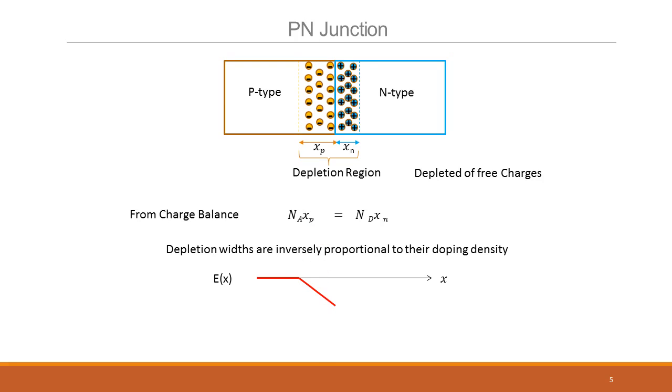Now, what happens as we go into this region from here? There will be some positive charges which are encountered now, which means the total amount of charge, inclusive of this, starts to reduce now. If the charge starts to reduce, the electric field tends to reduce, and it will become 0 back here, because the number of positive charges equals the number of negative charges. So the net charge in this space will be 0. So it has to come back to 0 at this point. And since there are no more free charge particles here, the electric field there will be 0 as well.